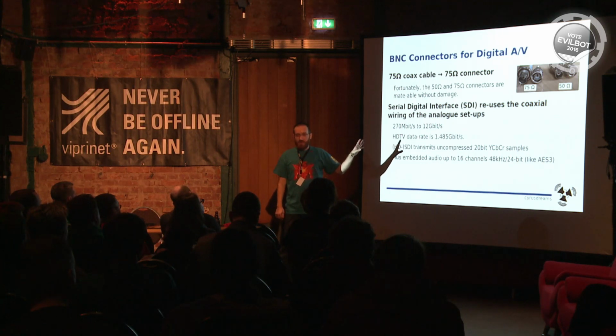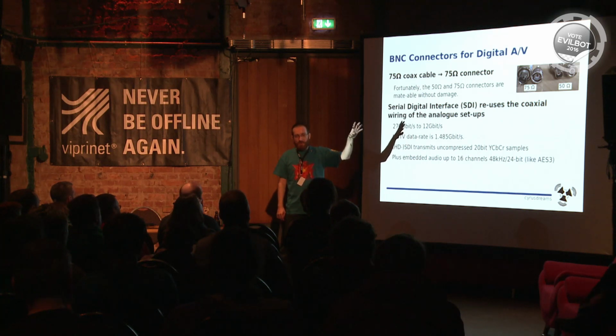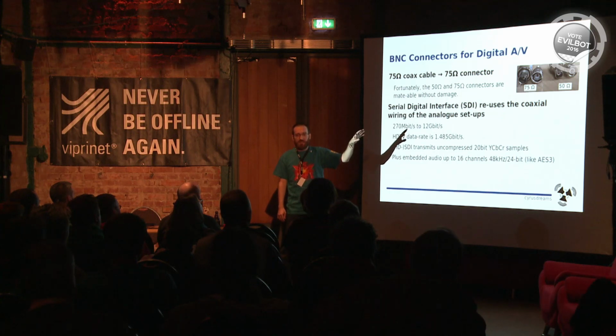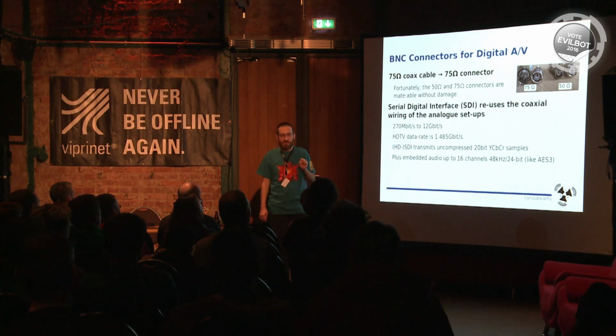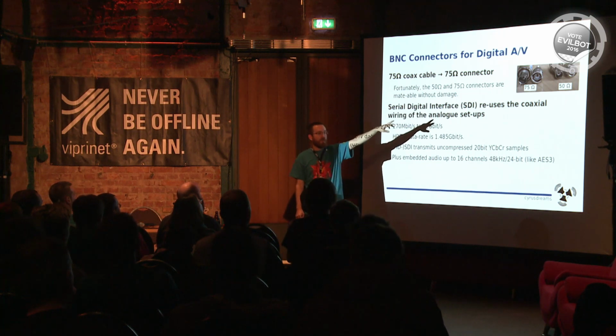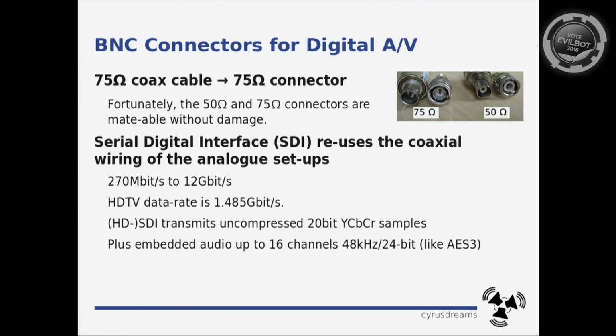And if you look at those cables that we have, the SDI cables, most of the time they are equipped with the 50 ohm connectors because at 3, 4, 5, maybe 10 megahertz, it is not 4 gigahertz where it really is a problem. So they just ignore that and use the cheaper connector because the 50 ohm connector is the one that is produced in huge amounts. The 75 ohm is less so produced. And additionally, maybe it's a bit more robust because of the plastic inside. You cannot break off these little contacts there.